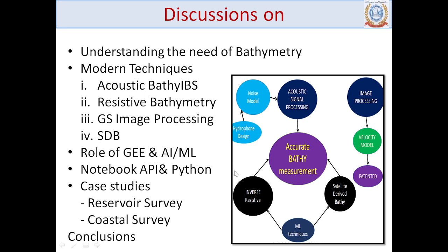Then possibly one or two case studies if time permits, which I will take up at the end: one reservoir and one coastal. We have tried the satellite derived bathymetry technique at three reservoirs in India. And in the coastal domain, we tried it at Andaman Lakshadweep Harbour Works, because you need a lot of data to validate the model also. So we validated with the bathymetry survey carried out by Andaman Lakshadweep Port authorities. Some water quality studies we have also classified for Calcutta Port Trust authorities, and for Goa, where we got access to measured dissolved oxygen and suspended sediment.